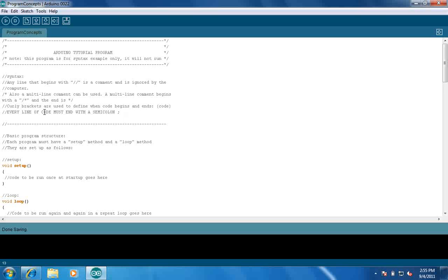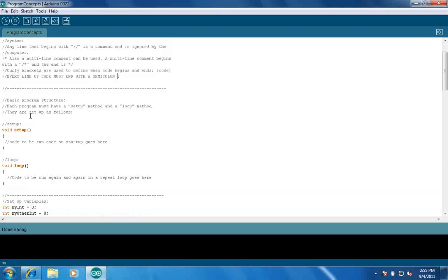But you can read through those. I want to get onto the more important things. The first thing is every Arduino program needs a setup method and a loop method. The setup method gets run once, and any code that you put in there is meant to set up your Arduino for the program that's about to be run. So if you have some constant integers you want to declare, or you want to set up your pin modes for outputs or inputs, it's usually a good idea to put that in the setup method. And in order for the Arduino to work, you must have a setup method.